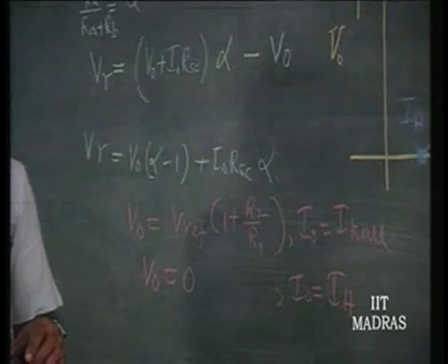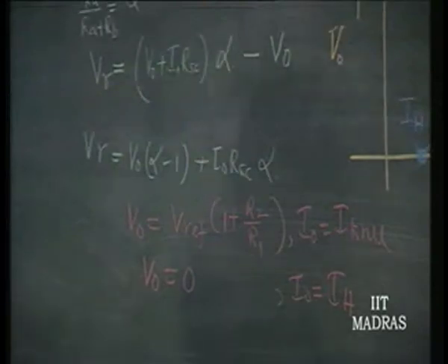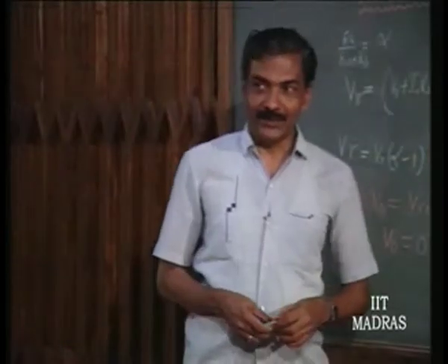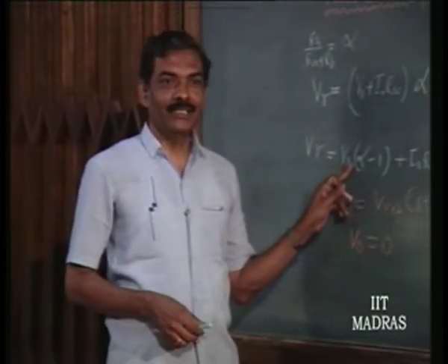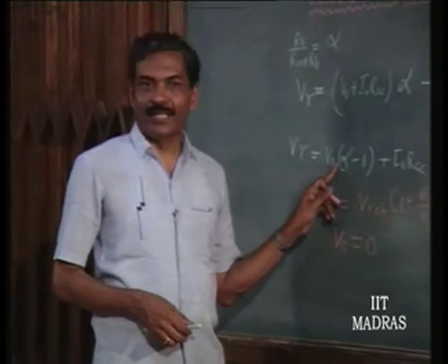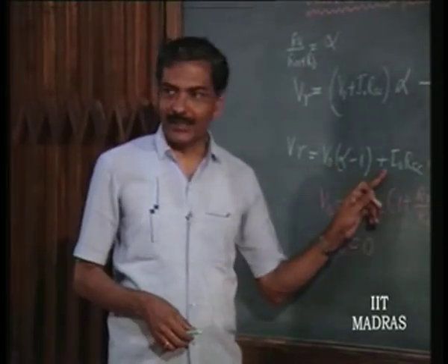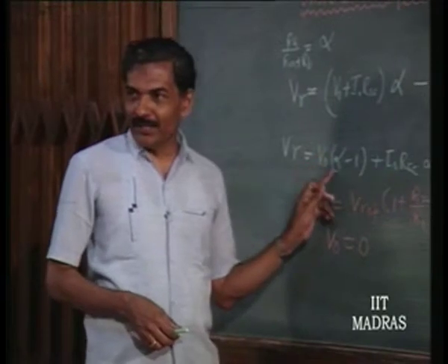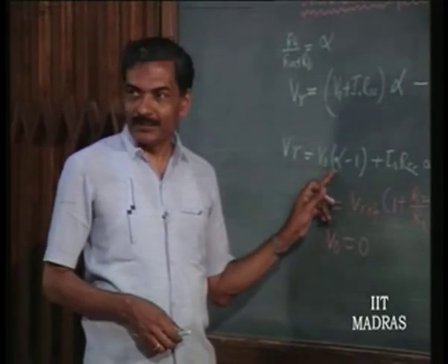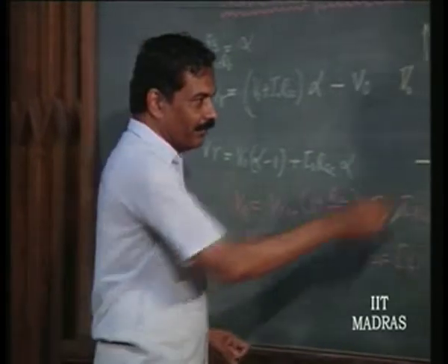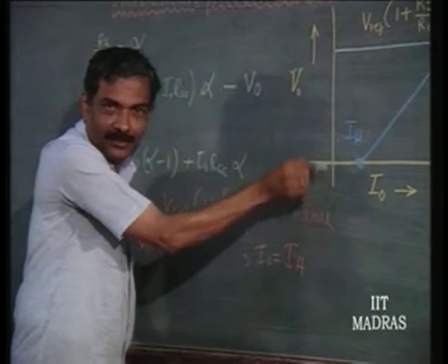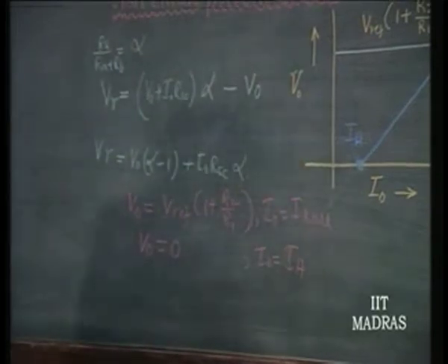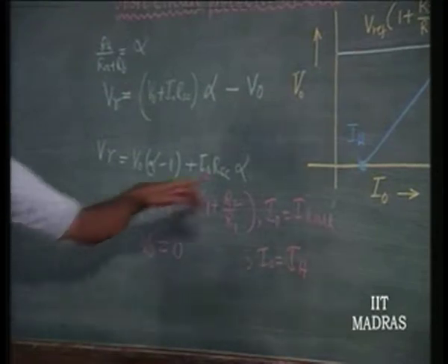The question is, can you make it very, very small? What is it that is going to cause problems? One thing that you have to see is alpha has to be less than 1. In solving this equation, you must have alpha less than 1. Okay? So, actually when I naught is 0, it should intersect at the negative value, which is magnitude of V naught into 1 minus alpha, right. That is that point.